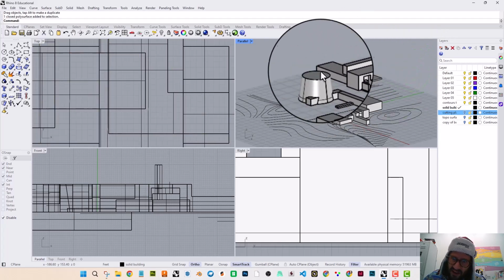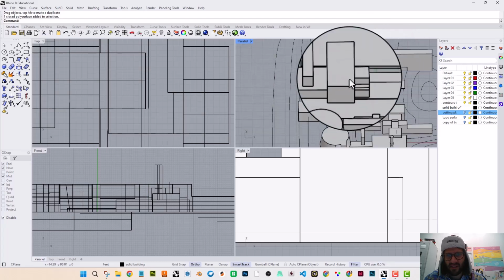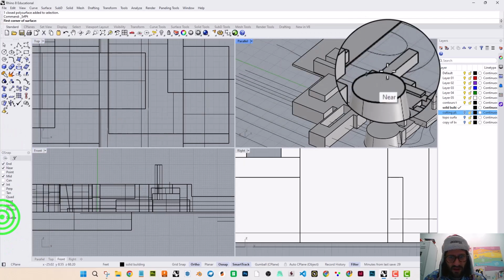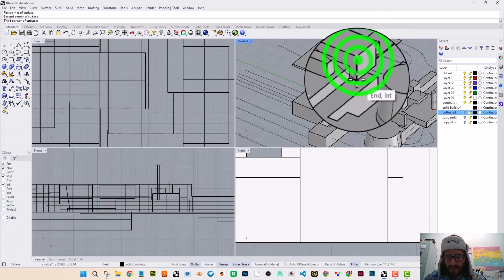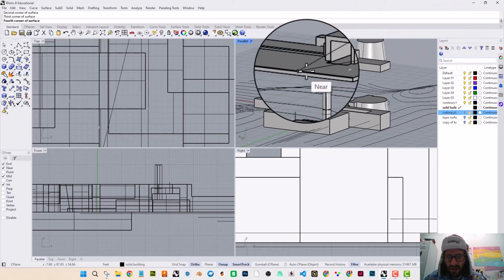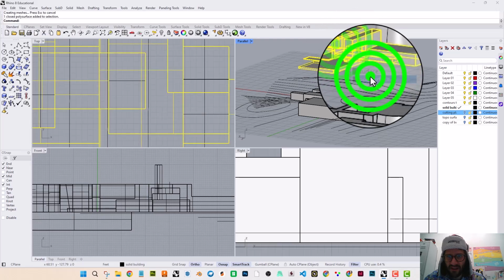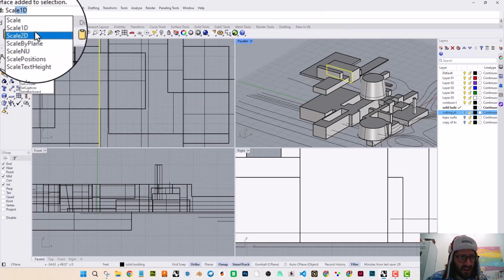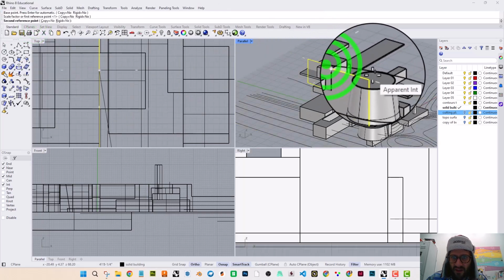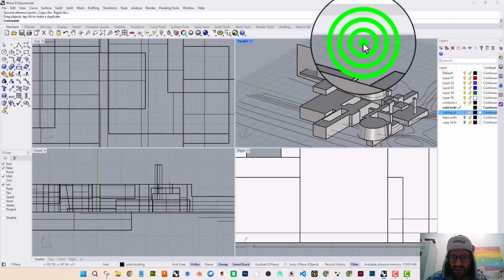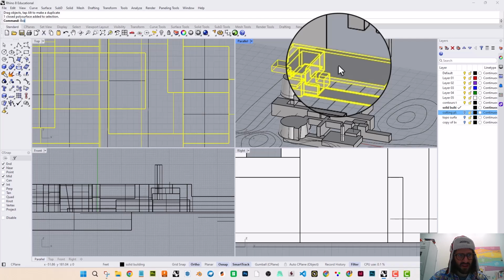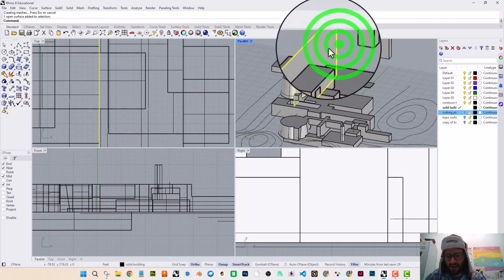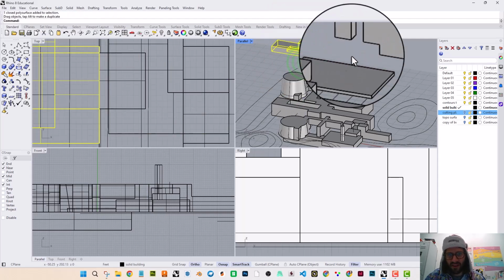Maybe this piece here could become 2 pieces. So I can add a plane here. Let me enable snapping. Click, click, click, and click. So now I have that surface. Oops. And then if I just scale it, then I can get it to cross through everything. Okay. So then Boolean split this. Boolean split by that. Enter. Okay. I don't need that anymore. And now that's its own.